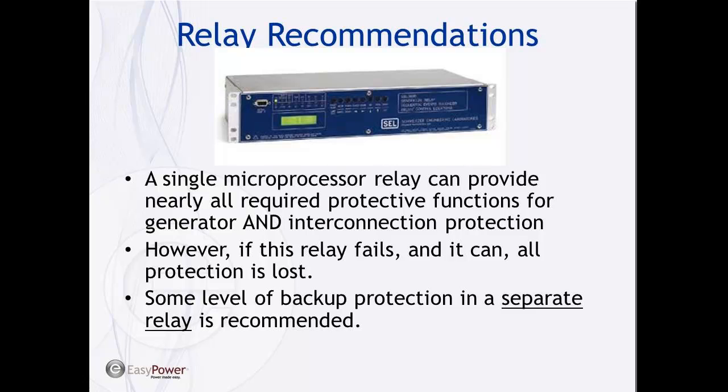All right, just to get down to the issue of what relay should I buy, there's lots of relays out there right now that can provide generator protection, and so you're going to want to get some type of microprocessor or multifunction relay. So I can buy a single relay. This is a Schweitzer 300G, but there's other similar products available from other suppliers. That one relay can provide all of the protective functions and a lot of the interconnection requirements. So all the functions we talked about today can all be provided in this one box, provided you have the right CT and PT inputs into it.